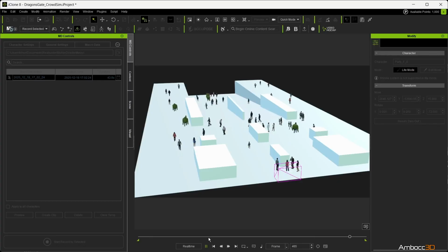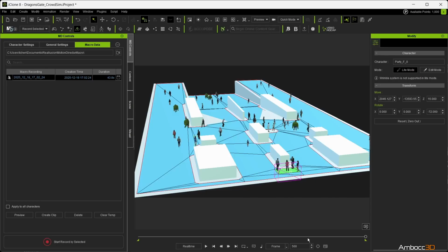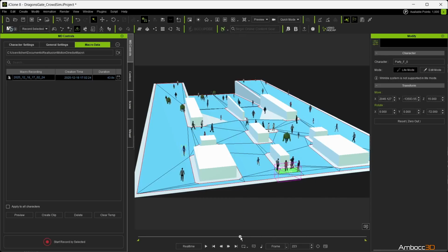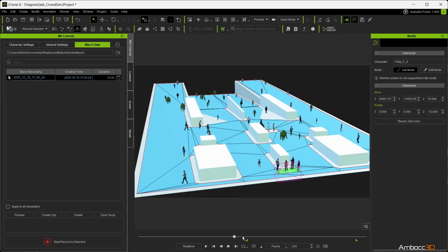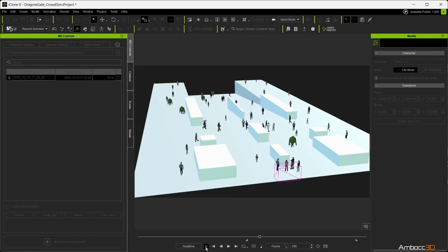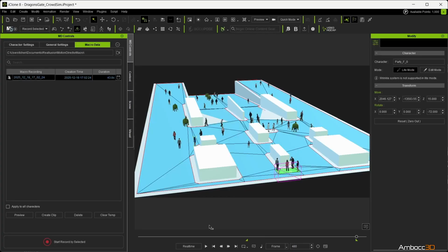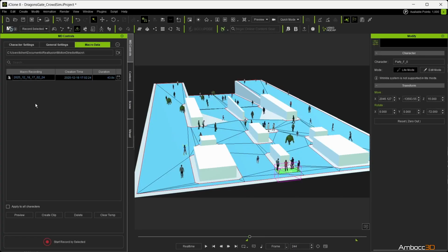And since we're recording only 240 frames, let's start at the second half of the 240 frame mark. So let's start at 241, and then we'll export out to 480. And we want it to go to 480. All right. Let's play that section again. That looks pretty good. I like it. So since we like the animation, I'm going to hit the Save button here to save this cache. This way, if I need to close out the program and reload it, I won't lose the data.